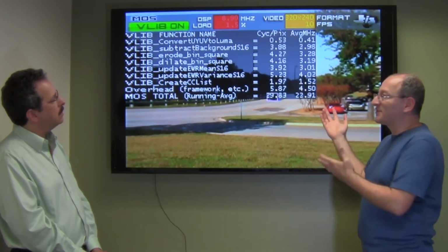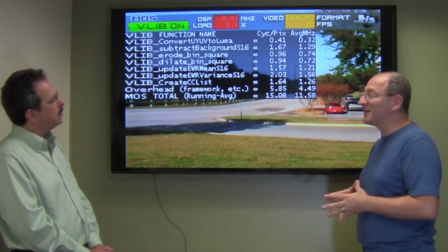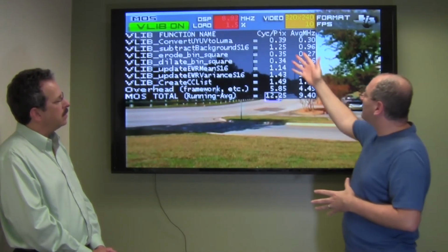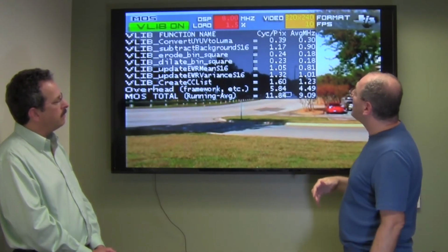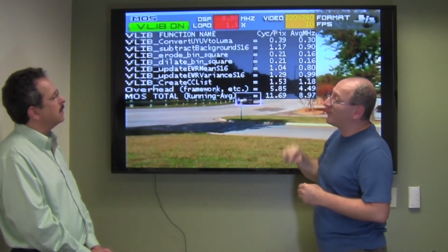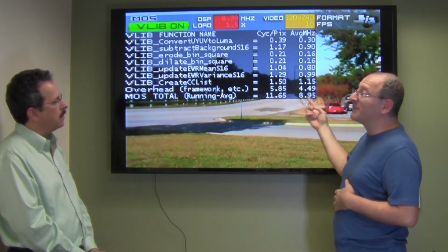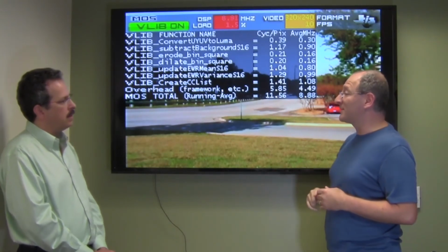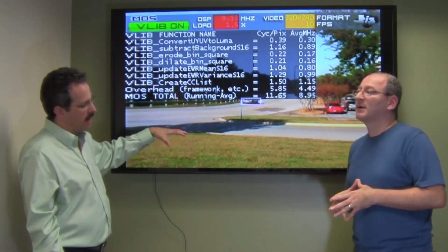The nice graphics in this graphical user interface are due to Darnell J, who did an excellent job in putting together this demo. There's also some very simple temporal filtering going on to get the numbers better behaved. So you remember the 15% loading? It is now down to 1.5%. More specifically, from 86 megahertz, we went down to about 9 megahertz, because we are now using DSP optimized code, which includes the DSP optimized versions of the TI library functions.